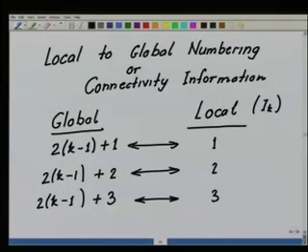Okay. So remember what we have done. Before we go and do the element calculations, we have set the entries of the global stiffness matrix and the global load vector equal to 0. The process of assembly that we had talked about in great detail in the previous lectures essentially is adding the elemental contributions to this global stiffness matrix and the global load vector in order to complete the global equations. Because what we had said is this integration over the full domain can be partitioned into the integrations over the elements.